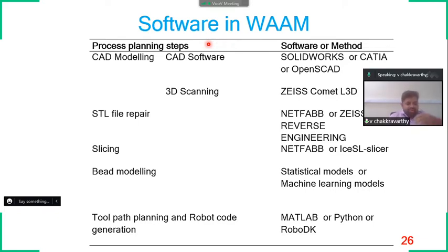Of course it will be doing. But if it is doing as it is, then it will lead to a lot of errors. It is because the geometry will be very complex, meaning the machine cannot understand exactly in which trajectory it is supposed to move. So it will leave a lot of trajectory errors. In order to overcome such errors, we will do a process called slicing. Slicing means a very big geometry will be sliced into finer segments, so that the machine can easily understand in which trajectory it is supposed to move. That is called 3D slicing.